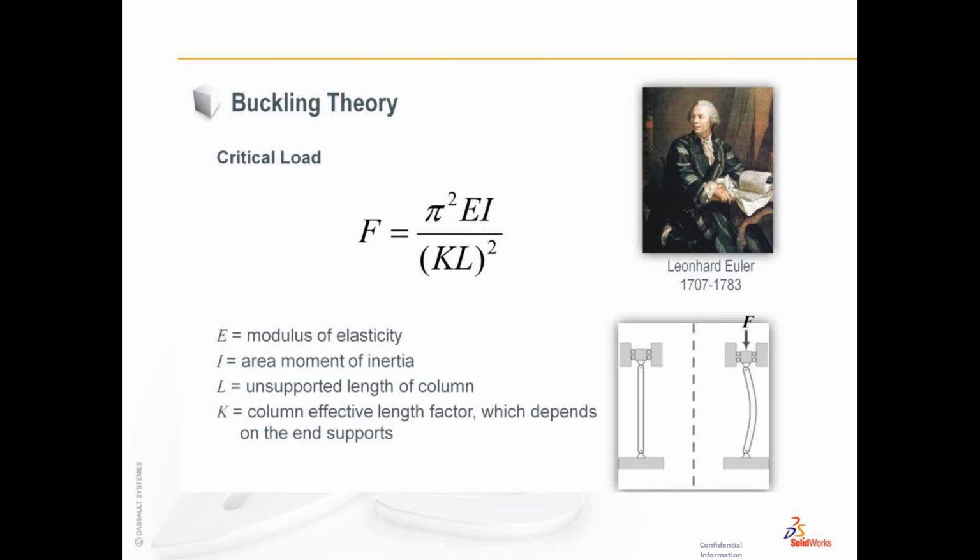The bottom terms here are what we call the characteristic or effective length of the structure. Now L is the actual physical length of the structure, but the K term is used to adjust the effective length resulting from the types of end connections that may occur. So your structure may be rigidly held at both ends while it's under compressive loading, like a support column.